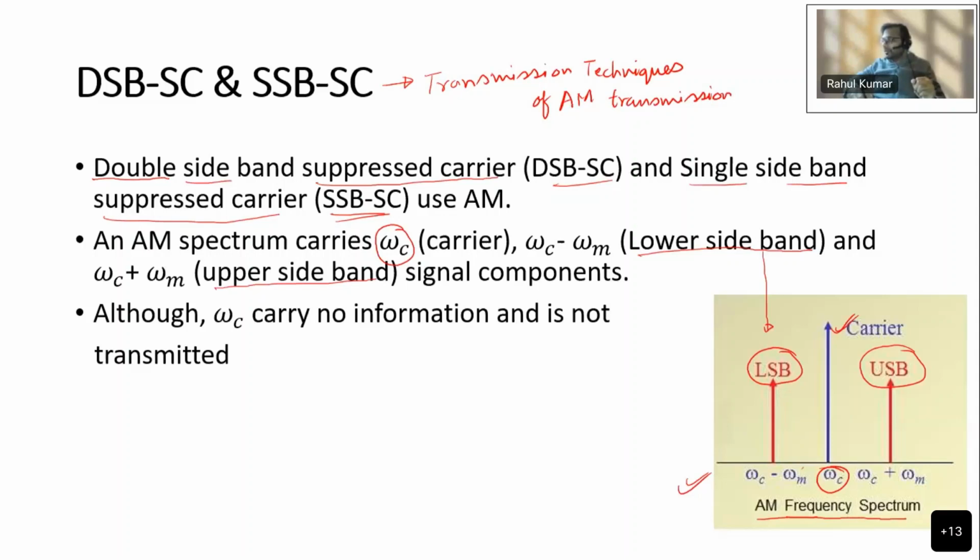So basically, some frequencies in the amplitude modulated signal will be less than the carrier frequency and some will be higher, because you are either adding or subtracting the message signal. Accordingly, this will be the frequency spectrum of your AM signal.